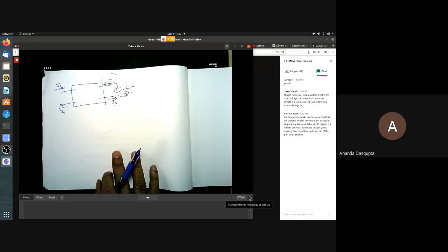The difference between a battery and a current source is not in the fact that one produces extra voltage and the other produces extra current. The difference simply is that for a battery, the voltage between the two ends is almost fixed by the battery itself, by whatever chemical processes go on inside the battery. I say almost fixed because for an ideal battery, it would have been fixed.